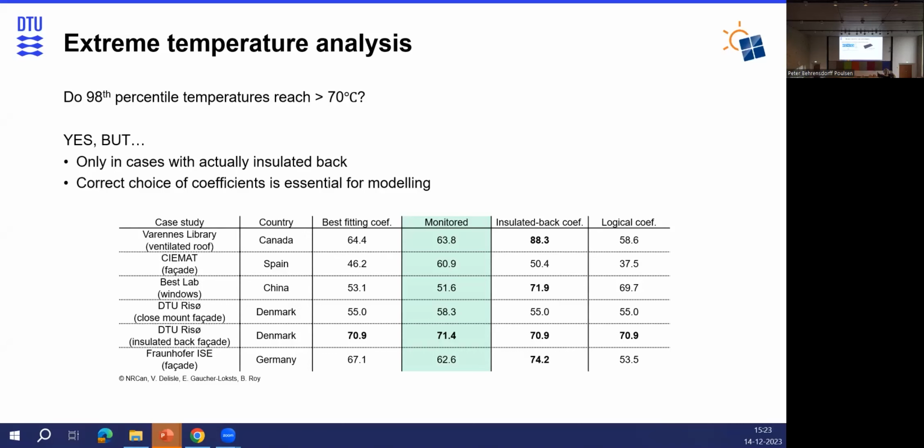And that means that the statement that we have in our technical specification, which says whenever you have an integrated system, you have high operating temperatures and therefore need to do extensive high temperature testing, is maybe not that valid. So our colleagues in task 15 are going now to the standardization bodies and are discussing whether we can affect the new versions of these standards to make it a bit easier for BIPV manufacturers to allow for less testing needed.